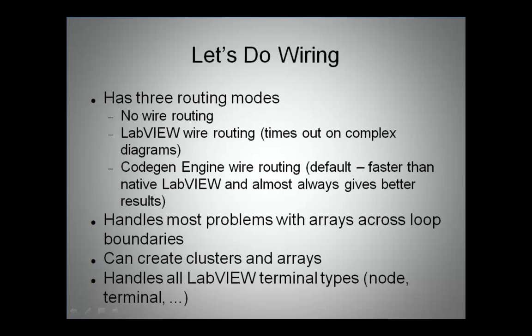The one I did was a depth first algorithm. It drops the wire, sees if it crosses anything, and if it does, it routes around it, sees if that crosses anything, and then routes around that. The downside to the one I created is it has no memory bound. It can theoretically eat all of your memory.